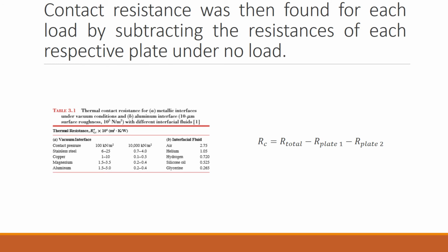After resistances were calculated for each load condition, the resistance across the interface between the plates could then be calculated. At first, the results were not encouraging. All of the contact resistances were zero. Upon further inspection of the book, the realization was made that the loading conditions were simply not enough to influence a significant change in heat transfer rates to thereby observe a contact resistance.